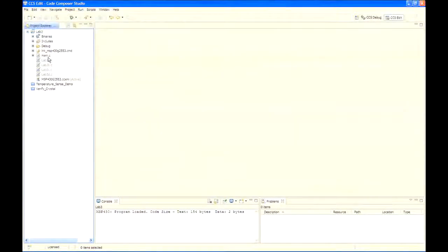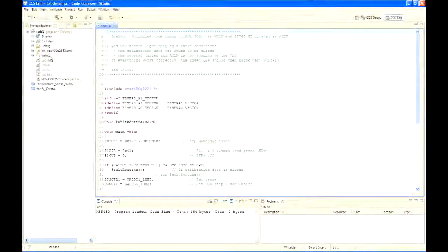So here, the lowest frequency at which we can run the DCO is 1 megahertz. So let's get started switching the M clock over to the DCO. In most systems, you want the A clock to run either on the VLO or on the 32 kilohertz crystal. Our A clock in our current code is running on the VLO, and we're going to leave it that way and just turn on and calibrate the DCO. So that puts us at step 31 in the lab.